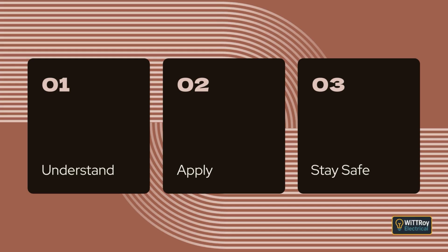Clause 2.9.3 Construction. Clause 2.9.3.1 Access to live parts. This clause explains how a switchboard must be built so people are kept safe from live parts. Live parts must be enclosed so that basic protection is always there. The enclosure is the main safety barrier that keeps people from touching anything energized. There is one situation where live parts may be exposed, but only in non-domestic electrical installations. In that case, the live parts must still be arranged so that barriers give basic protection, or the area must only be accessible to authorized people, with proper lockable access.